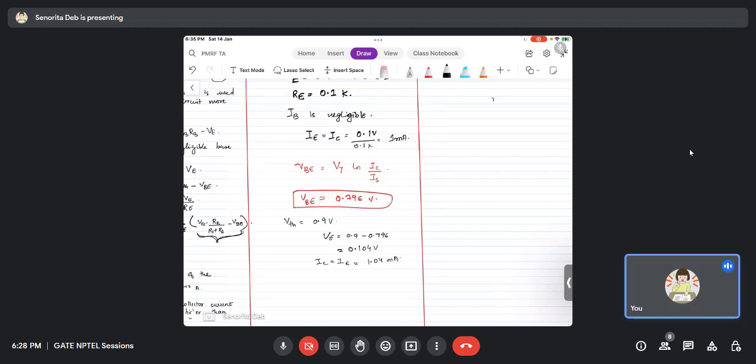So the linear graph, how it goes, right? Since now the dependence is all linear, inside the exponential the RB/IB term is not there, right? Therefore you are seeing that the 4% variation of VBE does not affect your collector current much, okay? Because we have made the IB negligible with the help of the emitter resistance, okay?